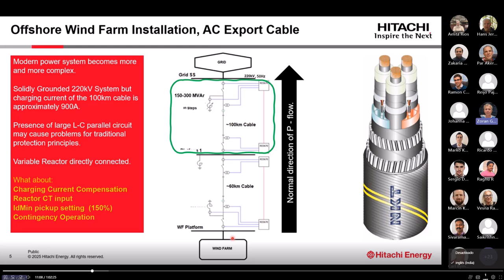And what is a little bit special for the wind farms, the commissioning phase can be months, even 1 year to 2 years to finish the commissioning, because you're dependent on the weather. It's a very harsh environment. What is very specific here, the commissioning phase can be very long, and during some parts of the commissioning phase, maybe the cable is energized, but the reactor is still not delivered, and they will have different operating scenarios which they need to cover.